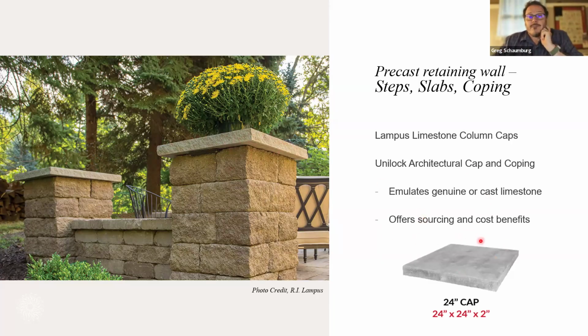So there's a few of these. There can be a little bit more sourcing and cost benefits in these products because they're really predictable. But again, depending on the one, you can recut the limestone ones and it'll be just fine. You can't really recut these because the inside surface mix is going to look like a broken piece of concrete. So you really have to think forward as to what your end dimensions are going to be before you start to shape them, if you're going to make changes with it.